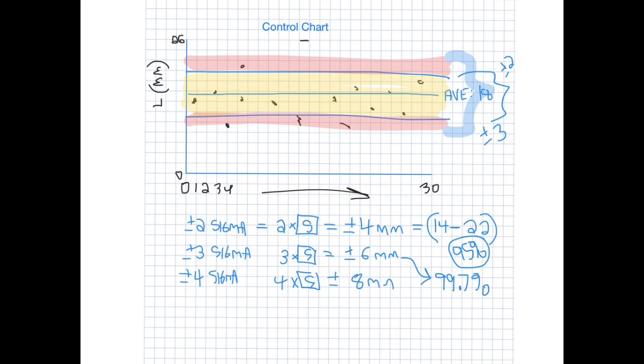If I'm a tool operator at a factory and maybe I'm turning a shaft on a lathe to a certain diameter, and maybe they're making thousands of these, so they don't need to measure every part. They'll measure maybe every 10th part. And every 10th part they'll put on their control chart. You can do the control charts by hand, but nowadays usually there's software that assists you. So you'll enter that diameter that you recorded for the 10th piece.